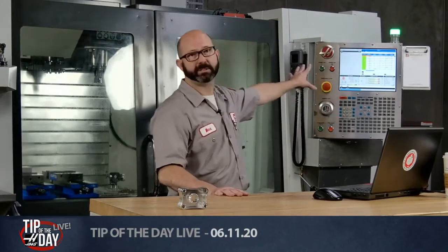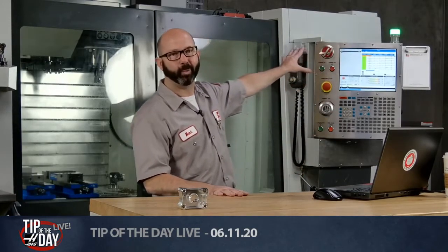So you've got a VF2, VF like this. It's a YT model, which means it's got extra travel in the Y-axis. And I'm assuming that they've got a shaft going sideways. So how do you probe that in the Y-axis? It's not that tough. You'll just use the VPS templates, and we have one called Y-Web.